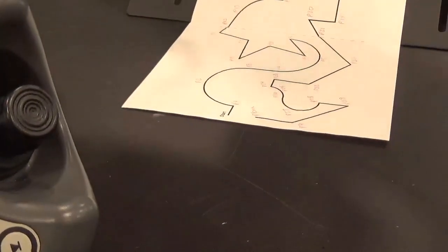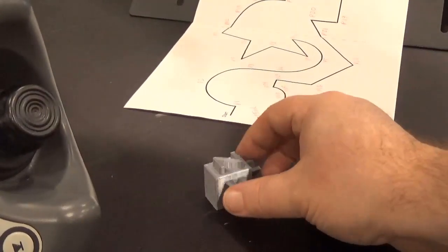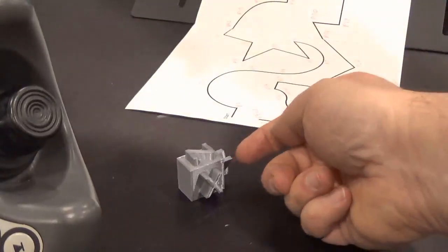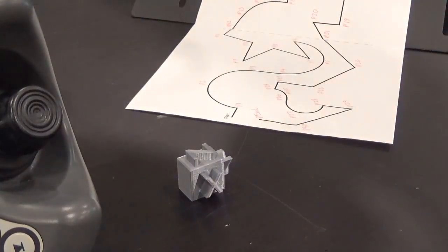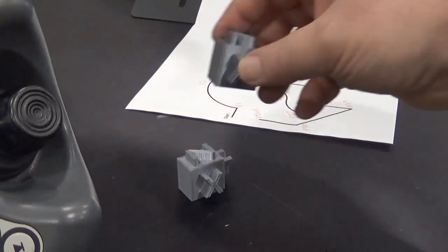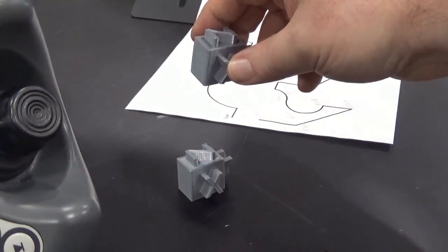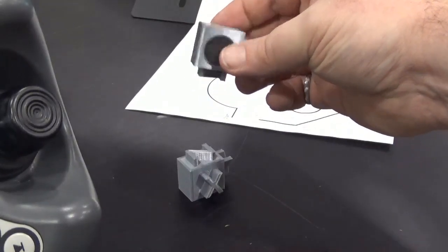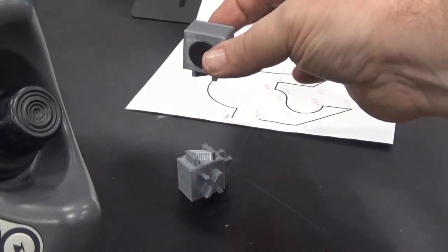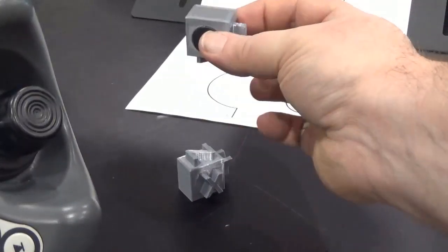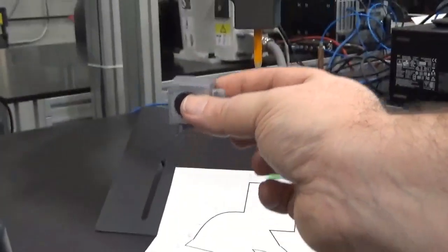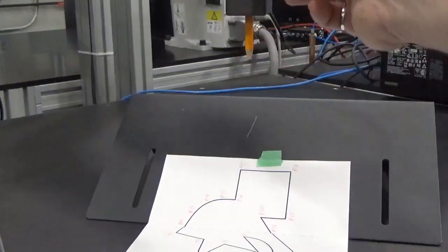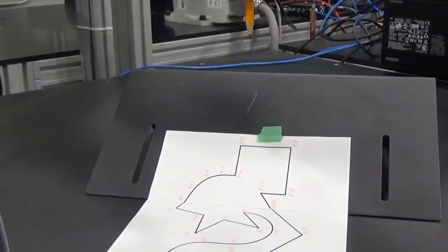when we were in the base coordinate system. Base coordinate system was basically X is positive here, Z is positive this way, Y is positive this way. Tool coordinate system is basically oriented to however your tool is. So in my case, it is like this. Z is down, Y is now sideways like this, perpendicular to the tool, and X is away from me in the positive direction.